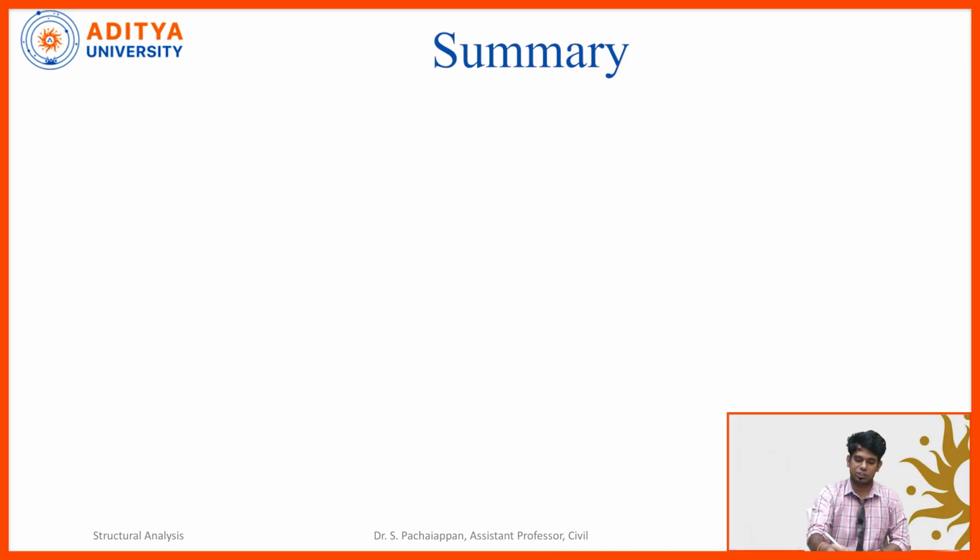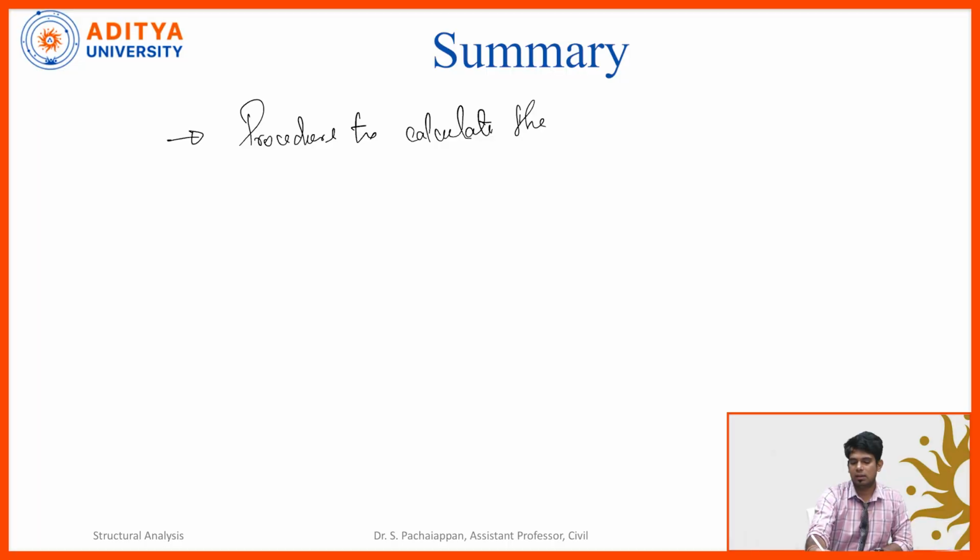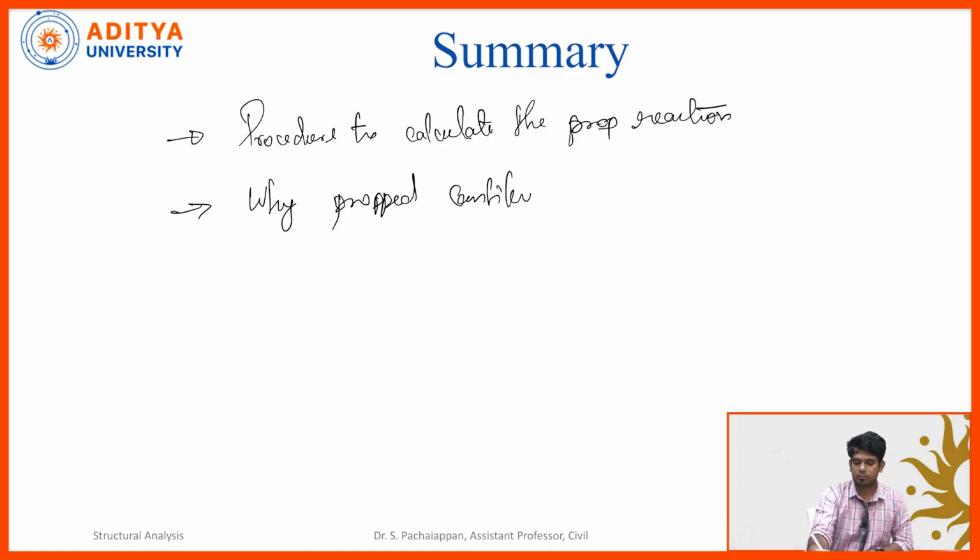So in this lecture, what are the things we have seen? We have seen the procedure to calculate the prop reaction, and also we have seen why a propped cantilever is statically indeterminate.